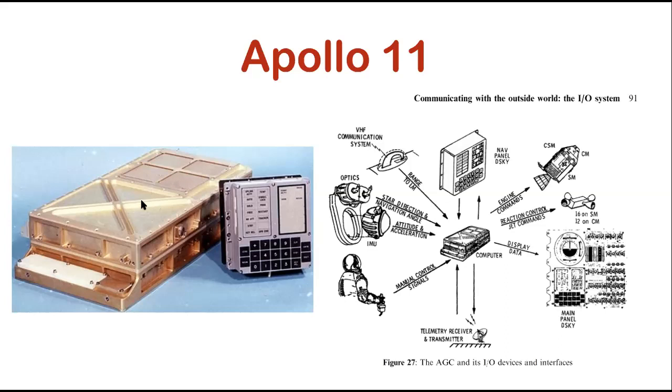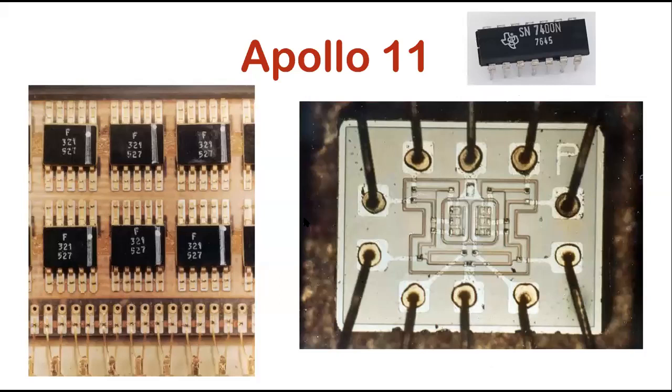If you popped open this box and look inside of it, it looks like this. These are called flat packs. And these little terminals, they're not NAND gates. So the Texas Instrument one was NAND gates. These things are all NOR gates. But if you then pop one of these things open, it looks like this. And all they did was figure out the same engineering problem you did. How can I wire that up so these terminals perform certain logical operations?